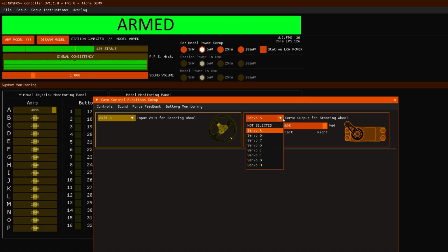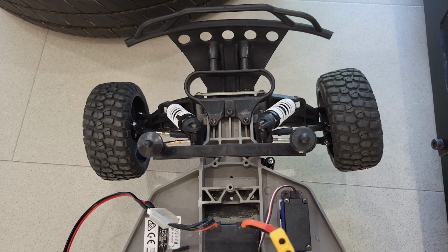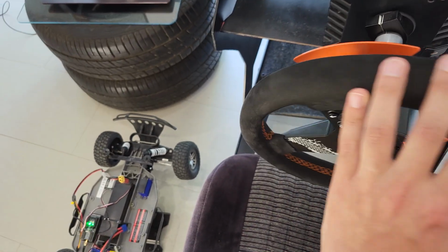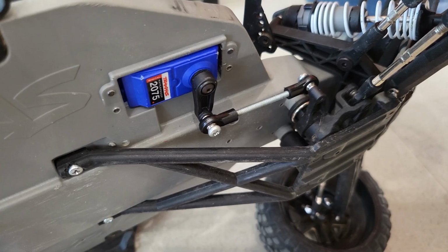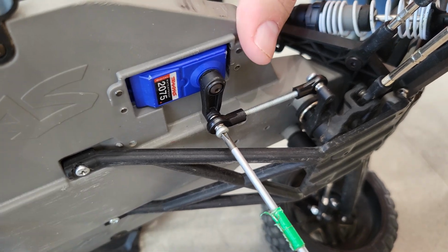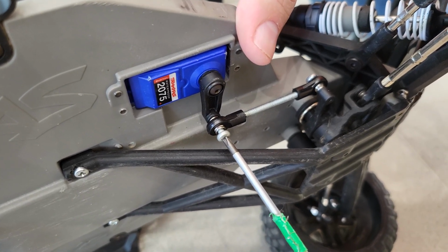At this phase of the setup, we are ready to install the link shock sensor, but before that we are going to disassign the servo by clicking at Not Selected. That way we will not be able to steer the servo anymore, but it is going to maintain its original position during the installation process.